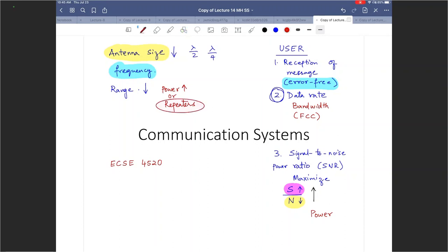So if this is an optical transmission, repeaters are, I believe, every 80 kilometers. So every 80 kilometers, you will see a repeater where you actually regenerate the signal, and we are able to regenerate the signal because in today's world, we do digital communication, not analog communication. So you will be able to regenerate those zeros and ones and have a repeater every 80 kilometers. But all these aspects are related to each other. Okay, I think